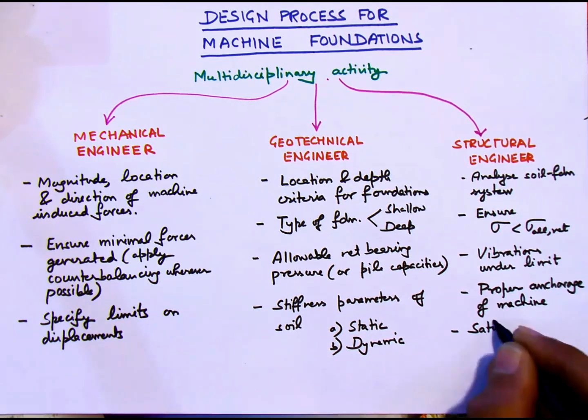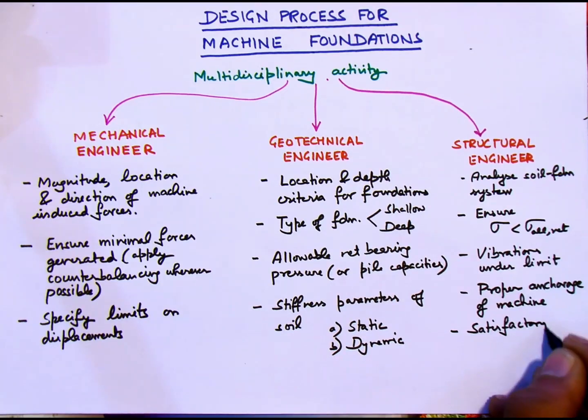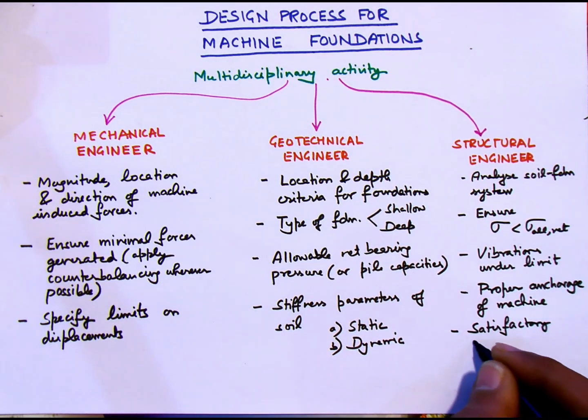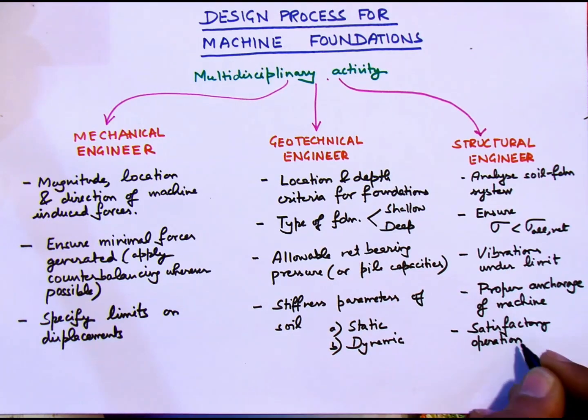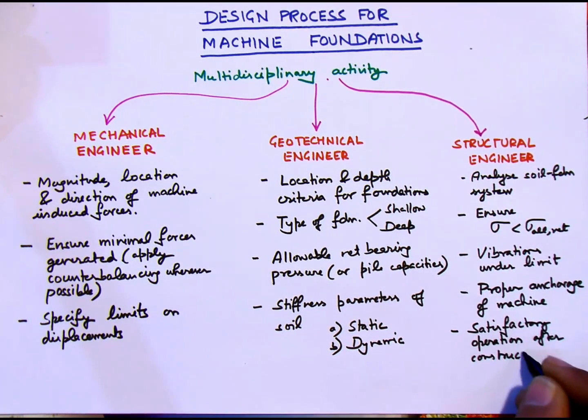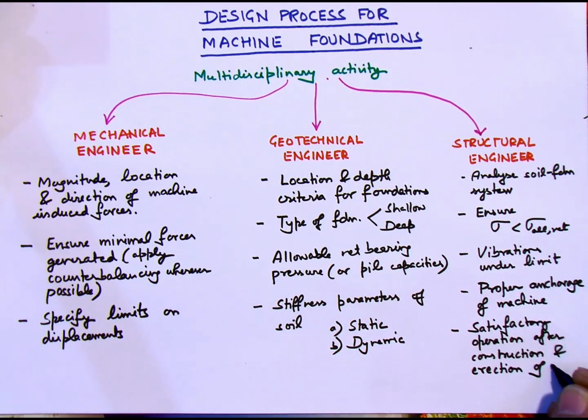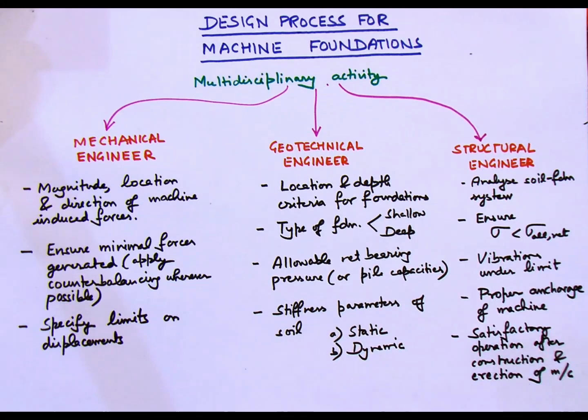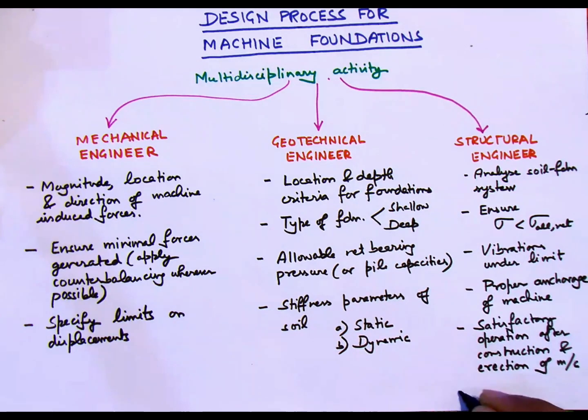So after the foundation is constructed and the machine is installed over it, it's also the responsibility of the structural engineer to check for vibrations while the machine is under operation, and for this purpose necessary measurements are to be made, and it is to be ensured that the vibrations in the surroundings of the foundation as well as on the foundation are within the limits.